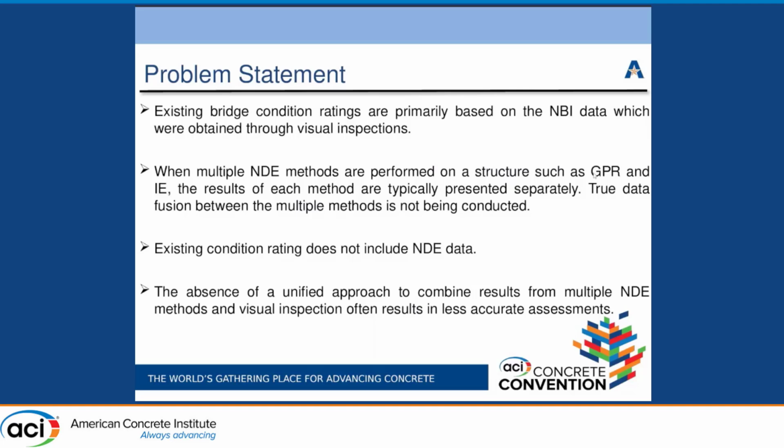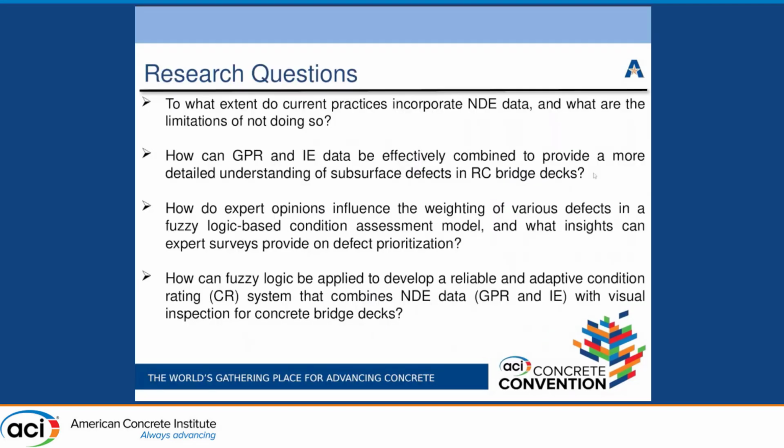inspection. Like I mentioned, Dean and Gagarin did a lot of research and tried to have a number from the GPR ratings, but their research only considered GPR, which is only the corrosion aspect. The internal delamination within the structure was not considered. Other types of defects that could be within the structure, such as cracks and voids, weren't considered.